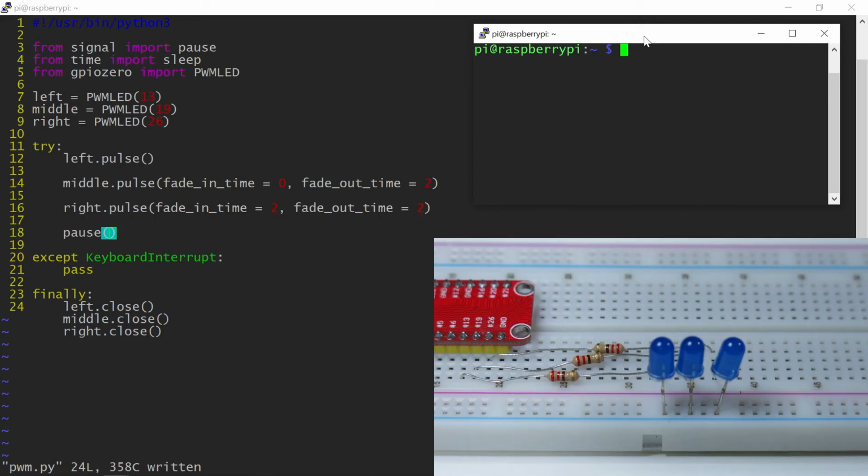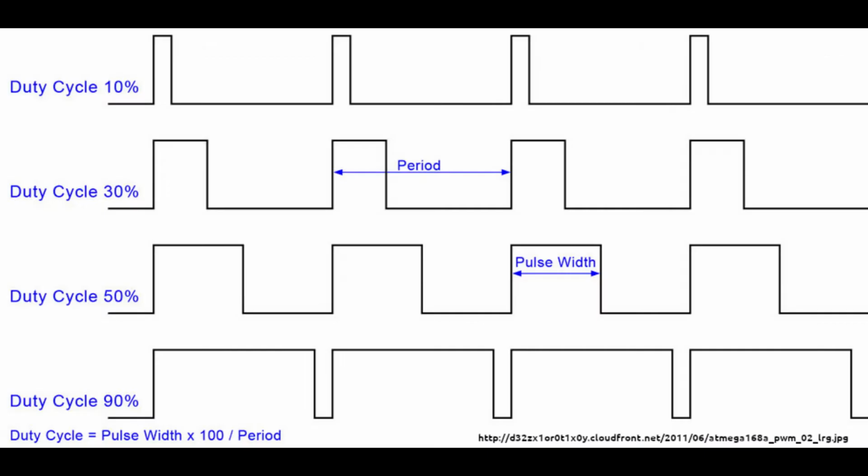Hello! This video will explain the concept of pulse width modulation, or PWM, when applied to LED brightness control using Python with Raspberry Pi. Using PWM is a common method to control brightness of LEDs, whether they are small, what we use on a breadboard, or in standard household lighting. Pulse width modulation relies on rapidly cycled DC power, resulting in a square wave.